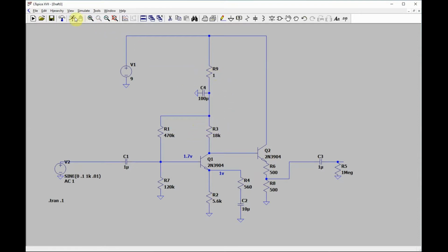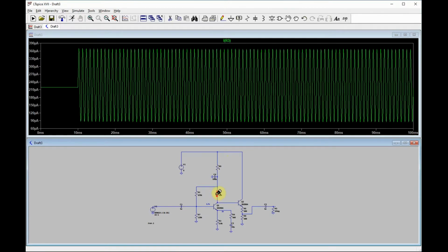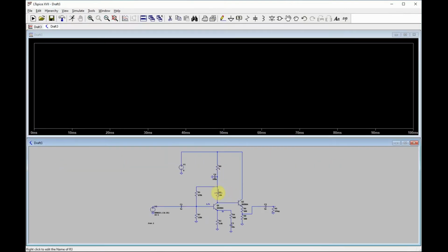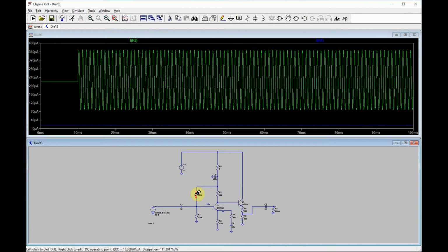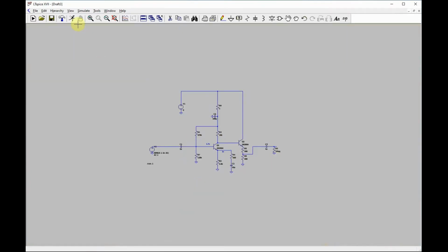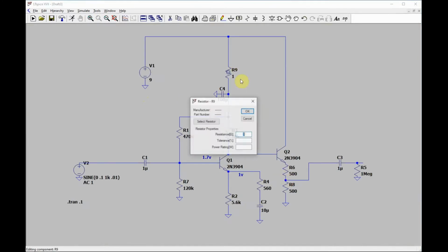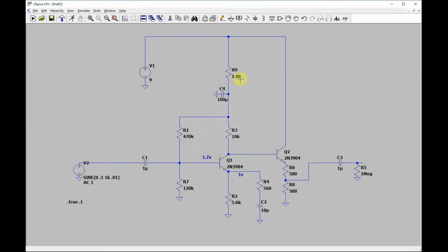But we've got 210 microamps. So we're going to want this to be like 10 times lower than that, basically. And let's see here. Most of the current's going this way, which makes sense. And this is 18K. So I'm going to say that if we make this like 1/10 of that, then this should remain pretty close to 9 volts. I might be wrong. Let's check it out.